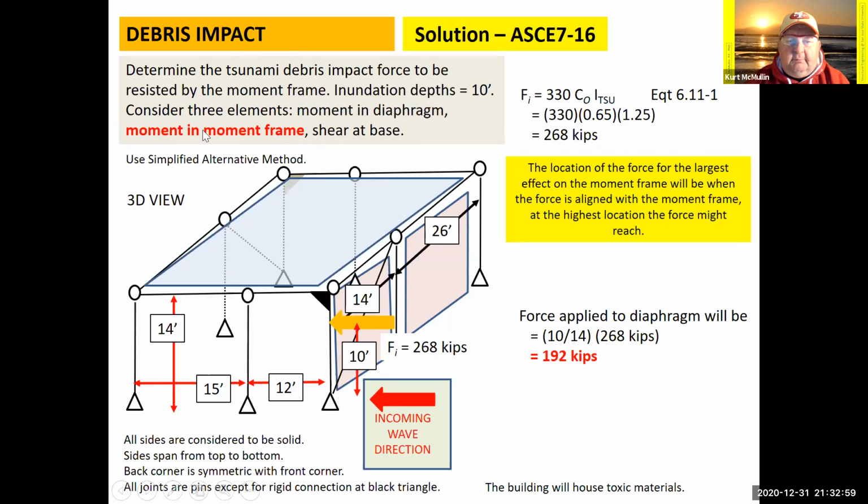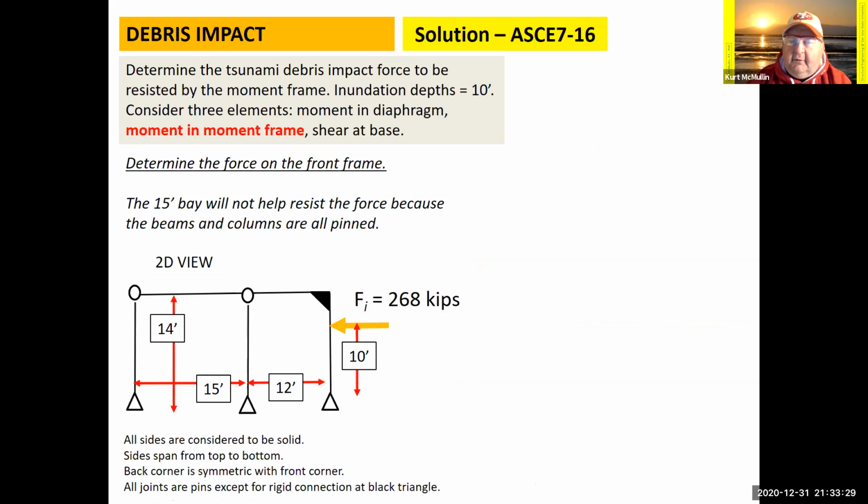If I'm interested in the moment occurring in the moment frame, well, the worst situation now would be that debris hit directly in line with my moment frame and at the highest point possible. So I'm going to have to assume that 268 kip force might be applied right at my moment frame, 10 feet away from the base.